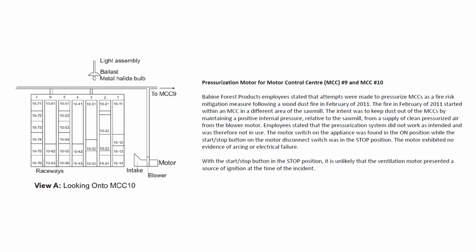Instead, they're built into a room that is positively pressurized with a fresh air supply. And that means that under normal circumstances, this room has a slightly higher pressure than the adjoining rooms. That means that you need to ensure that the doors to the room remain shut and that the pressure system, as in the HVAC system, intake, the blower motor, all of that remains operational.